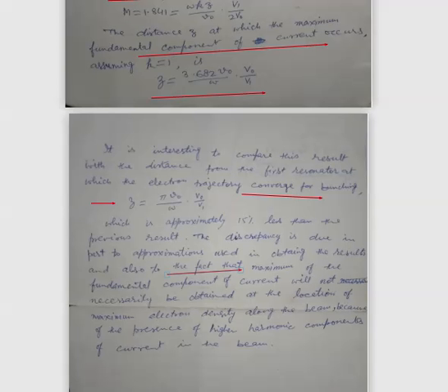AC beam current, and in our next lecture we will discuss that at this location z, if a second cavity, which is called the catcher cavity, is placed at this optimized distance and the field between the cavity grids is maintained, so that the bunches or clusters of the electrons will be retarded, then the energy loss in the kinetic energy of the electron bunches will be imparted to the fields of the second resonator cavity, which will be converted into the AC fields in terms of the generation of the microwaves. Thank you.